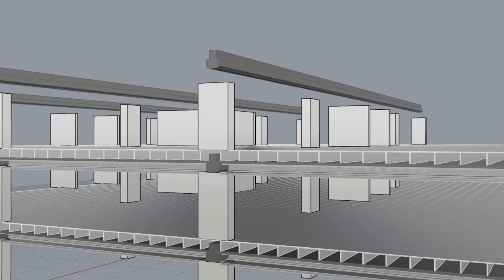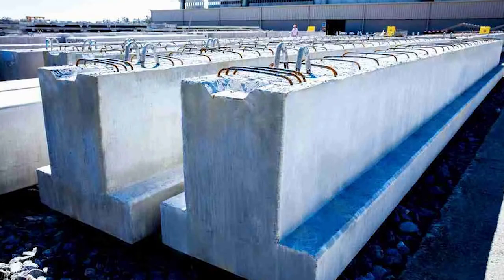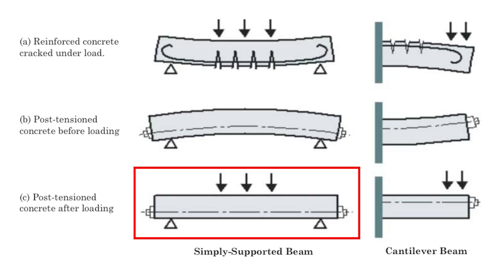Next, we'll move on to the girder. The girder and wall ledges were designed for the concrete reaction. In Abbey Park, the inverted T girders were used to achieve efficient load distribution, ease of installation, and reduced structural height. Also, the post-tension beam construction method was used. Due to post-tensioning, it can adapt seamlessly to complex and large-scale structures directly on site and can apply greater tension, supporting larger loads and extending the spans of structure.